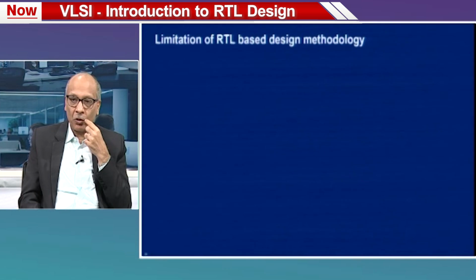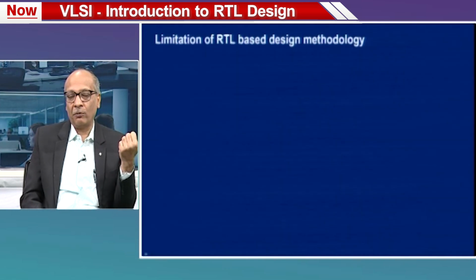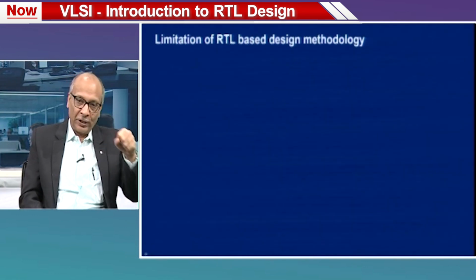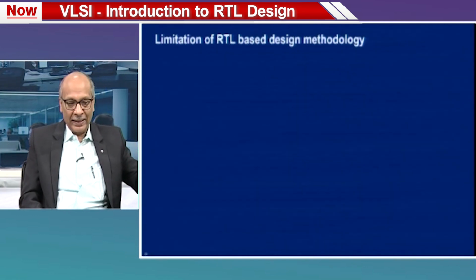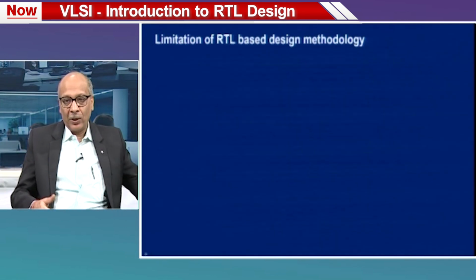So, what we have talked about so far was the advantage of RTL based design methodology, and also how we will take it to simulation and static checkers to verify that our RTL is correct, and then take it to synthesis to generate the gate level netlist, right. So far I have been talking about how RTL based design methodology is much better. So, does it mean that it solves all the problems? No, this RTL based design methodology also has some limitations, and we have not gone into the actual methodology other than synthesis. We will talk some more in a while.